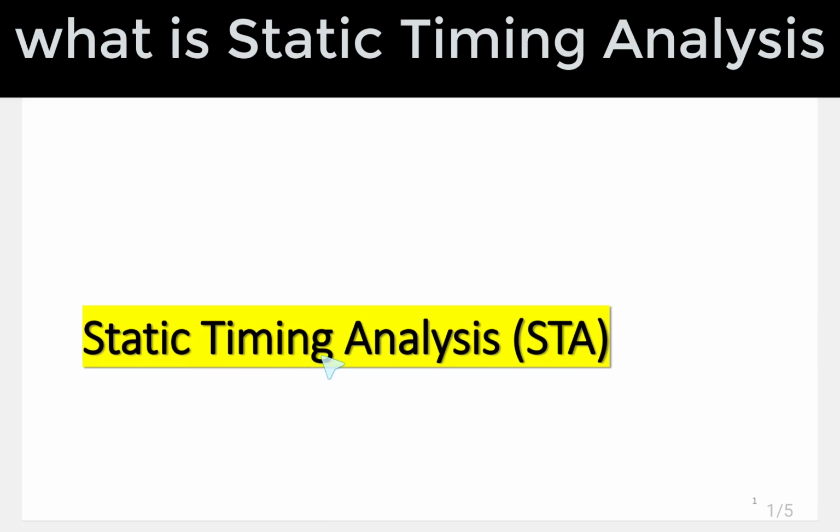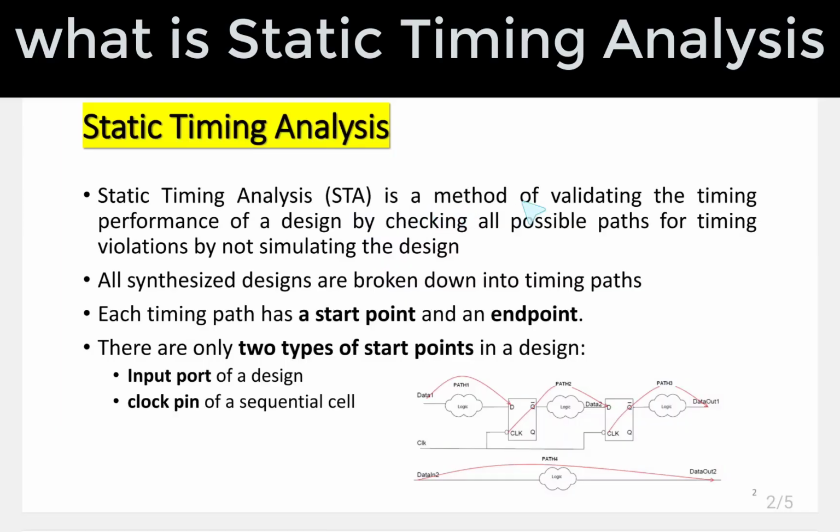Let us see what is meant by static timing analysis. Static timing analysis is a method of validating the timing performance of a design by checking all possible paths for timing violations, without simulating the design. All synthesized designs are broken down into timing paths.